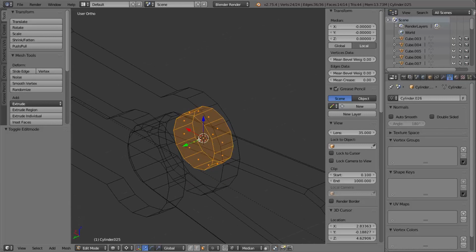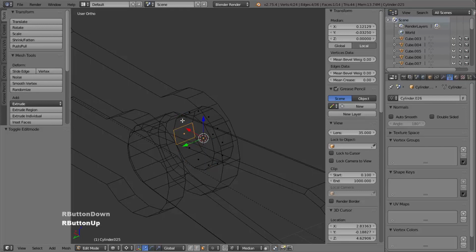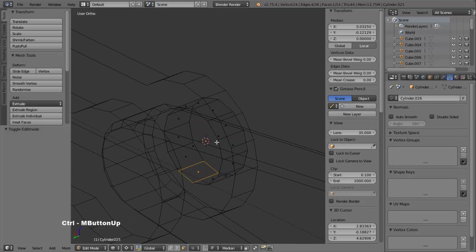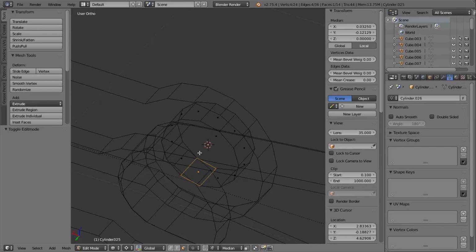And sometimes in these situations, especially in wireframe view, I find it quite difficult to make the selection that I want. I quite often misclick, and instead of selecting this face, I'm accidentally selecting one of the faces at the sides or somewhere that I don't want to select, basically. So in these situations, I find it useful to switch off the manipulator, and I can do that down here with this icon in the toolbar. And if I switch it off, it gives me a clear view of the dot that makes up the center of each of these faces, and I can do an accurate selection.